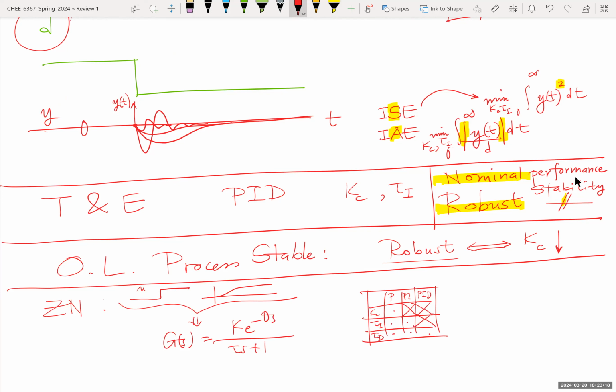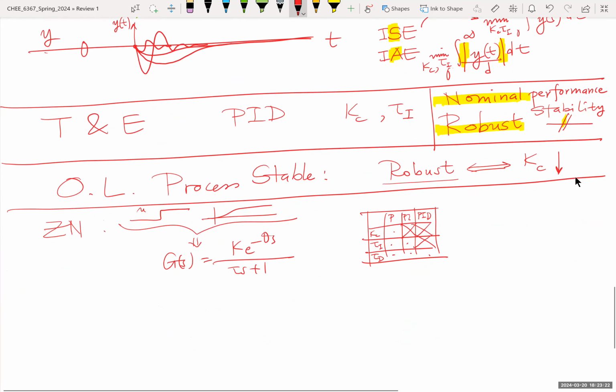And there are formulas. Those are not meant to be the ultimate, always usable numbers. In fact, even Ziegler-Nichols in their original paper in 1942, those have been around since 1942, and they're very good. There have been countless improvements, but I would say this is worth understanding. And in that paper, they tell you how you modify this. They tell you if you don't get what you want, well, change things in that way. You get too many oscillations, well, lower the gain a little bit, perhaps.